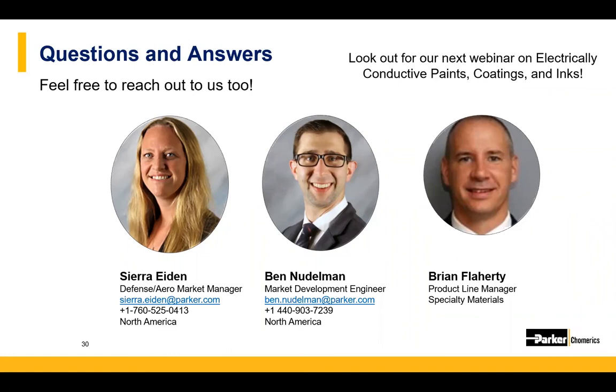We actually do have some published values on some of our electrically conductive materials as far as thermal conductivity goes. But you'd be surprised. There are some very highly filled ceramic thermal materials that get into the 7.5 watt per meter K range, whereas some of these may be in the 1 to 2 to 3 watt per meter K. I don't know if you have anything further for that, Brian. No, that was well said.